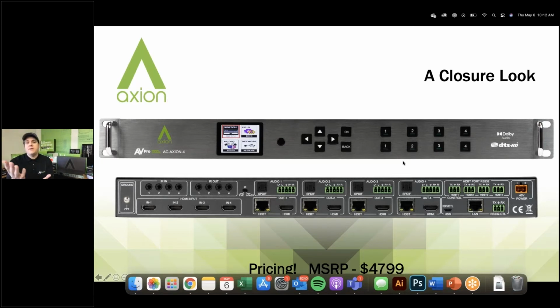Let's say you have a PS5. Let's say that you have an 8K display. Well, 8K displays do a really great job of upscaling that 4K signal to 8K. And so what you can do is manage your EDID inside this matrix switcher to ask for 4K 60 4:4:4 from that PS5, giving you that full 18 gigabit per second signal, which is a beautiful picture.